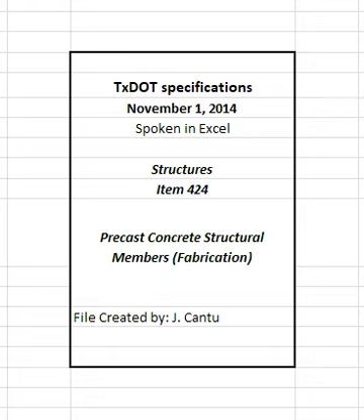4.2.2.2.2 Single and multiple straight strand tensioning. After initial tensioning, apply the required load to the strands as shown on the plans by means of single strand or multiple strand hydraulic jacks equipped with calibrated gauges. Verify the final load in the strands by observing either the gauge pressure or elongation and independently checking the other. The final load and elongation must agree within 5% of the computed theoretical values. Additionally, the final load and elongation must agree algebraically with each other within 5%.